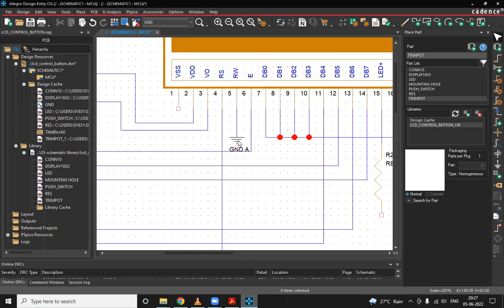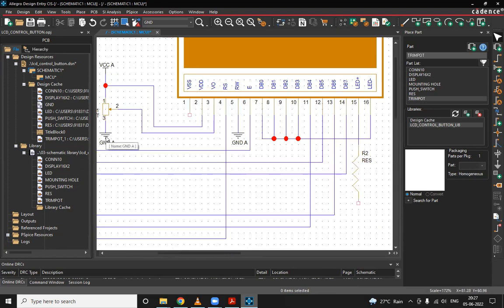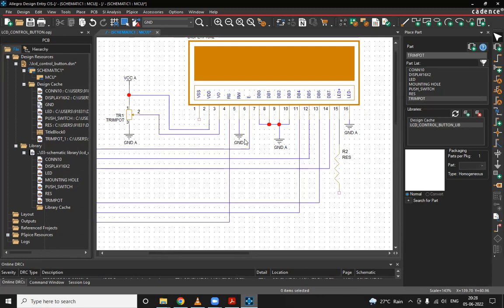Now if you see here, what is showing here? Ground A. Earlier what was it showing? Ground only. Now it is showing ground A. Right? This also is ground A. Control C, Control V. You can short here. Here wire. Clear? Here also so many nets need not cross. The same ground you can take. Control C, Control V, copy and paste. Clear? Now see, so many cross nets we have avoided, no? So many cross nets we have avoided here.